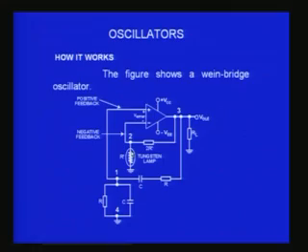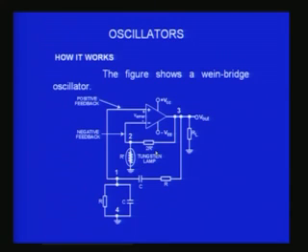So the gain of this will be 1 plus R2 by R1, we all know that for non-inverting amplifier. R2 is 2R, so 2R prime by R prime is 2, 1 plus 2 is 3, therefore the gain will be 3. That is what Wien's bridge condition says, the gain should be greater than 3.